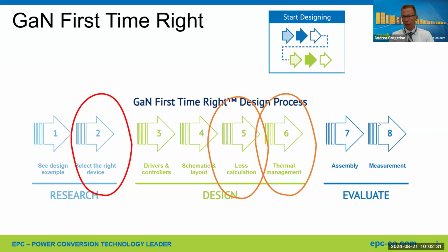And especially some of the tools like the SPICE simulations, for example, can provide quite detailed analysis in terms of losses and electrical behavior. However, to really be able to go to the design level accuracy required in these phases, there's a lot of extra work that needs to be done.